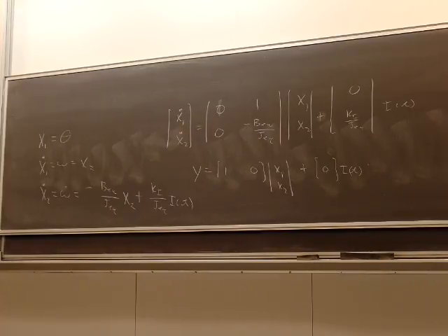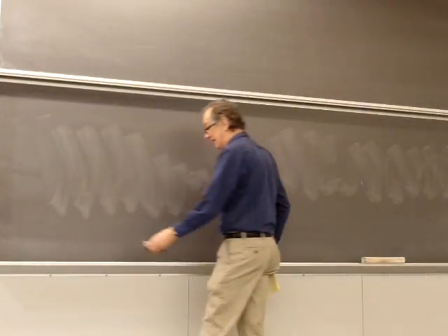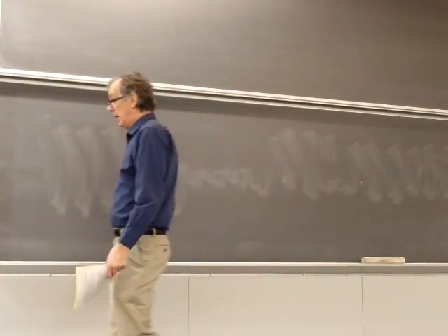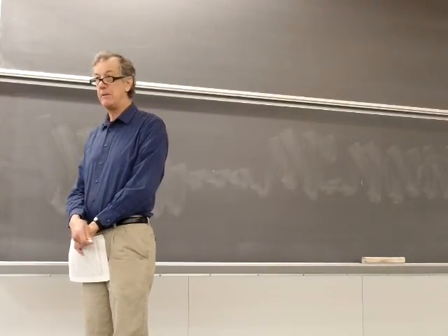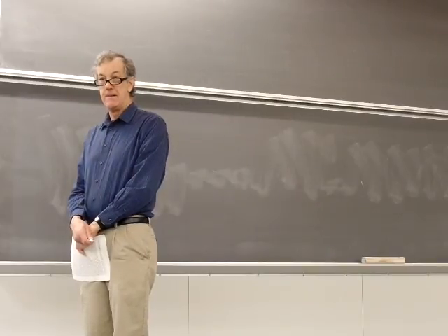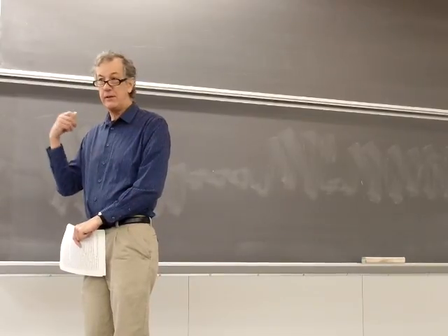Well, what are the eigenvalues for? Find the eigenvalues, it's a good thing. Do that. In some sense, I don't really care whether the open loop system is stable or not, because I can only stabilize it. It's nice to know. So, how do I get the eigenvalues for this thing? The poles, the roots of the characteristic equation. All right, hopefully you've set that as a neural connection in your brain now.